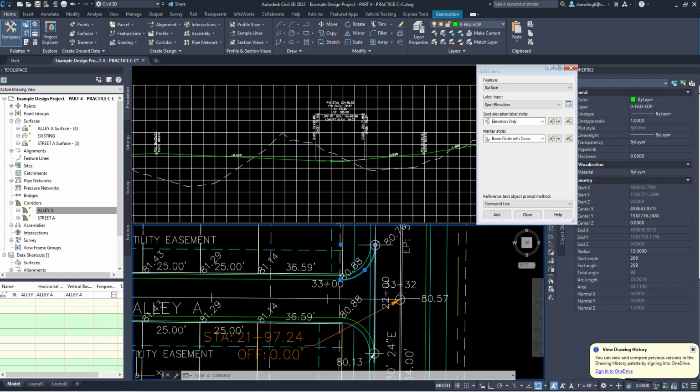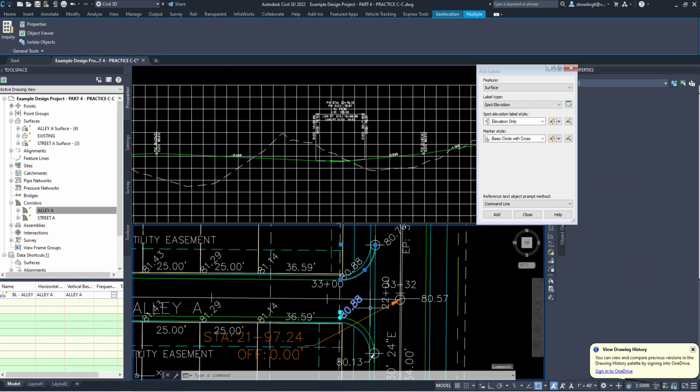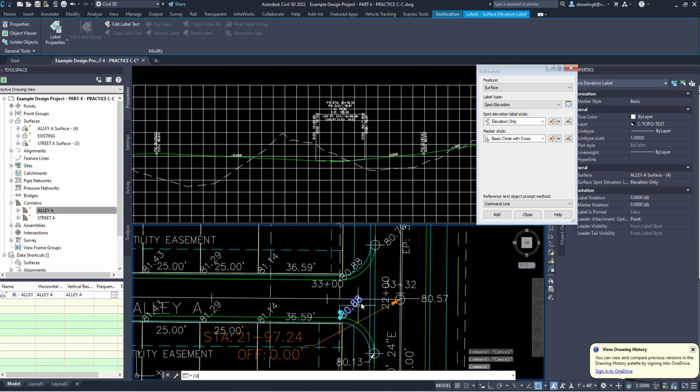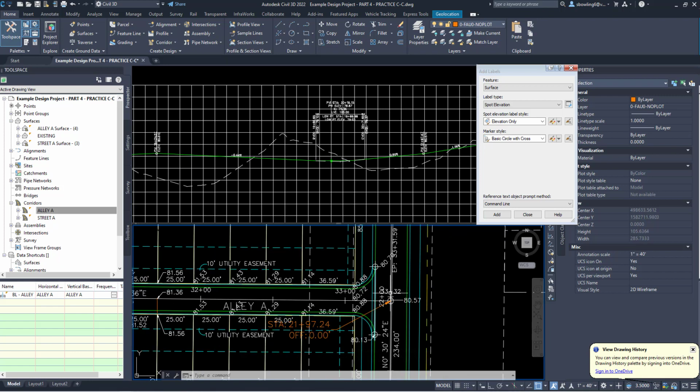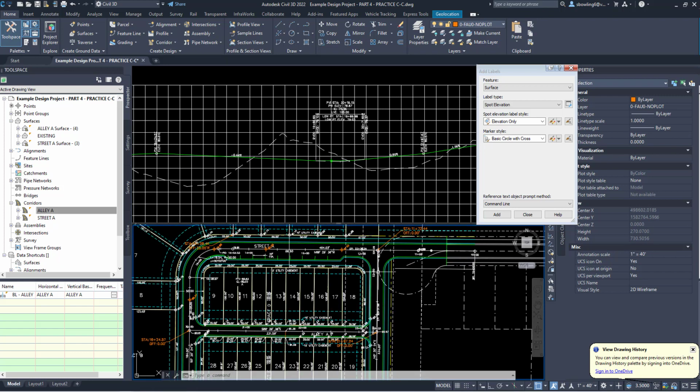So water is going to drain this direction, and then it's going to drain down. Okay, and this one's going to automatically. So I need this little valley gutter to keep this water, when it drains this direction, to slide this direction. Okay, now here's the other thing. This is an inverted crown, so technically the water is draining to the midpoint anyway. So if I copied this here, from here to perpendicular to here, we could see that I'm draining down to this point anyway. So I like the valley gutter here. The valley gutter is almost like a V swale, I'm sorry, a concrete V.